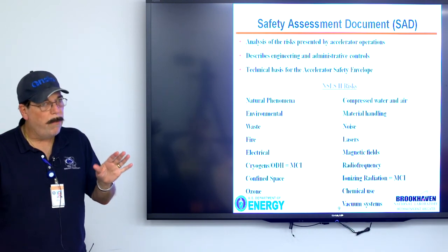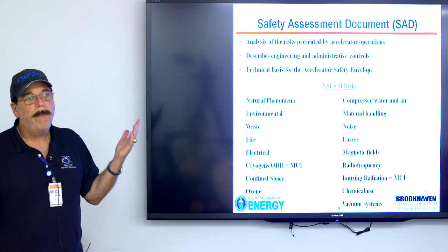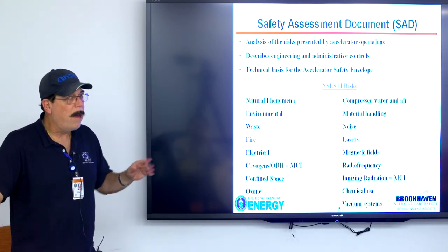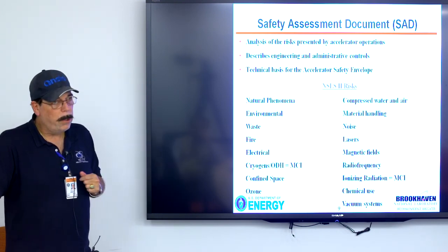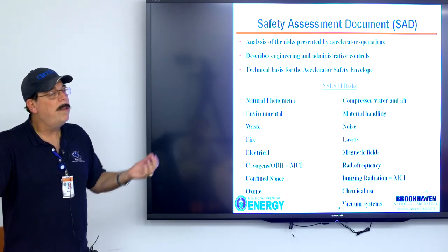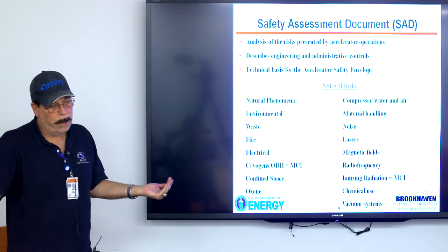What to do if we want to continue to operate in the enclosure if, for any reason, the ODH monitor is out of work, out of cal, or not working properly. We have those built into the process, the idea of these authorized alternatives. We also have the commitment to test them at a particular frequency and replace them at a particular frequency.